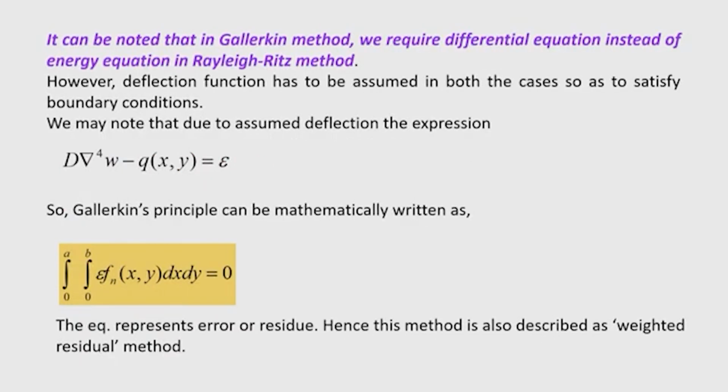It can be noted that the difference between the Galerkin method and the Rayleigh-Ritz method is that in the Galerkin method we require the differential equation instead of the strain energy expression.